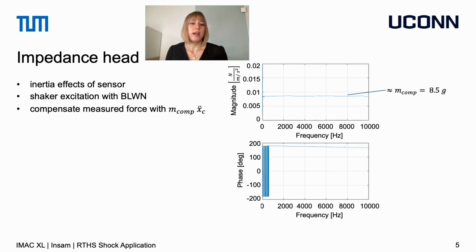So we needed to find out how heavy this portion of the impedance sensor is that creates these inertial forces. So we measured the transfer function of the impedance head, and we did this by exciting the shaker with band-limited white noise and recorded the acceleration and force signals.